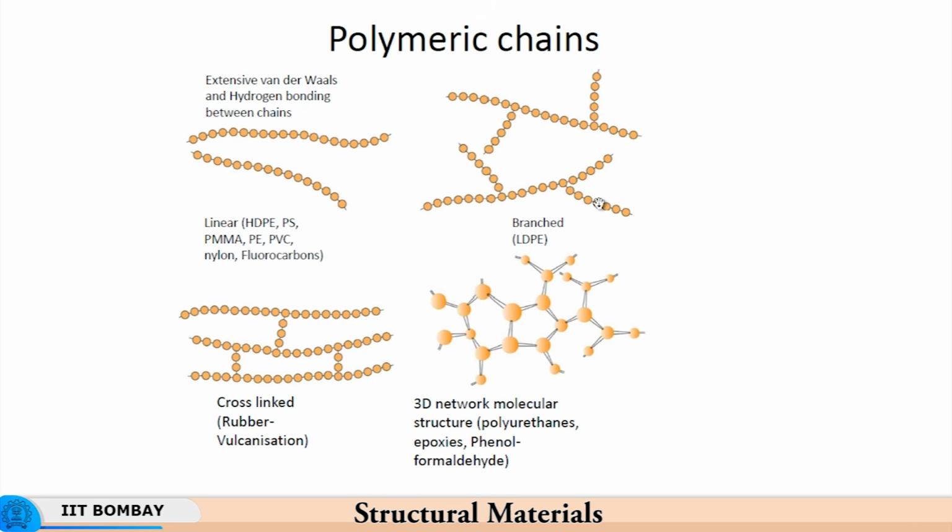Now when you subject a material to compression or elongation, what you are doing is you are elongating a bunch of molecular chains. You are elongating or compressing together a bunch of polymer chains. Similarly, when you are doing extrusion, you circumferentially compress the polymer chains, try to bring them together as well as elongate them in the direction of extrusion. So all this results in alignment of the chains, their unentanglement, and then you have uncoiling, unbending of the chains,